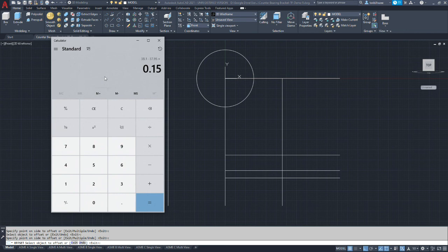We will now divide that in half and add it to the low end of the range, which is 37.95. That gives us a keyway width that should be 38.025 to be at the mean of the tolerance.